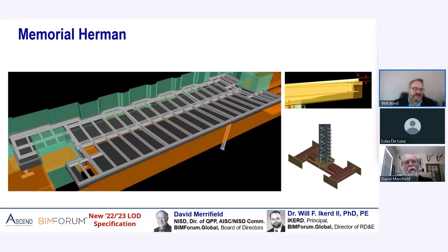One of the things that came out in the case study that I noted is there are air shafts here coming up from the parking garage below. What is in green here is the 1950s facade, and then gray is the new structural steel. You can see the type of foundation systems that would be cast in out in the sidewalk area, which is above the parking garage below. And then what kind of architectural finishes did this have on it, Dave? That basically had a metal roof and a metal fascia system.